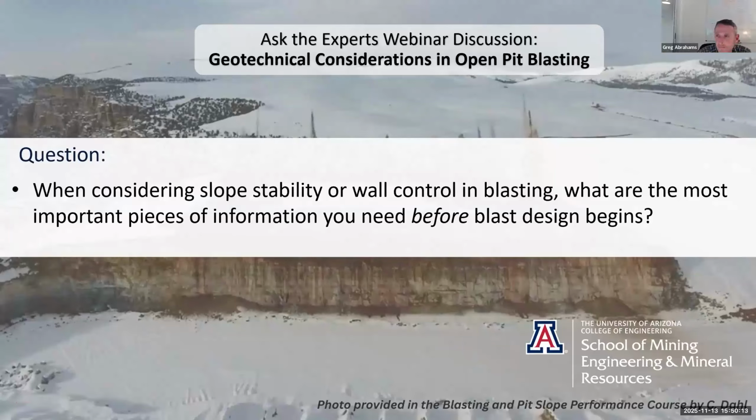Yeah, I suppose I could add just one thing that I think about, which is the actual capability of the operation. Often, you can't ask for the moon on a stick if you haven't got a stick, and I think that applies to blasting. You may want the best pre-splitting and the best drilling accuracy and really fancy loading if we're putting in decks and all this sort of stuff. But are the guys on the ground actually capable of doing such things?